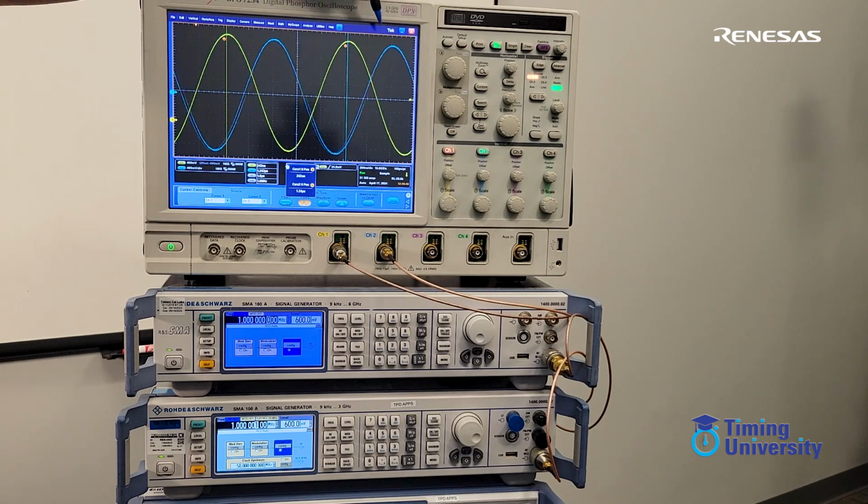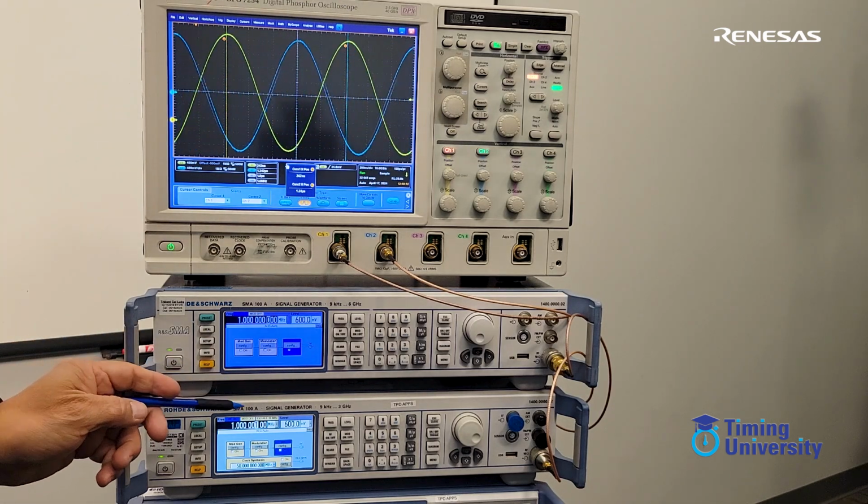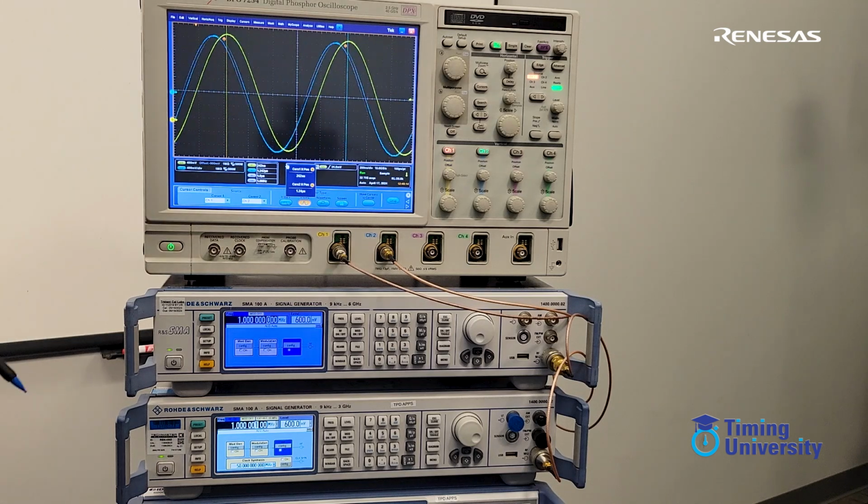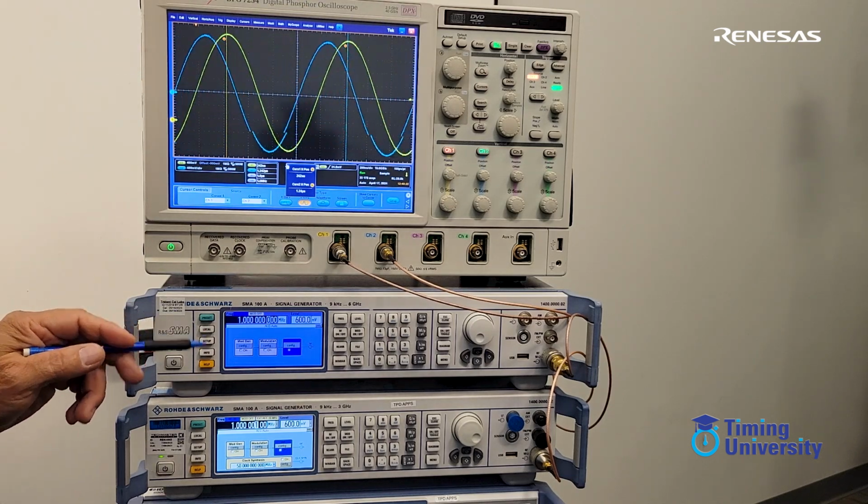Now we can actually quantify the frequency deviation by looking at how quickly this edge moves. It actually takes 1 second for this blue edge to move from this peak to this peak. So we measure it here. Again, we can measure it starting here, and it takes it 1 second. And that deviation, or that distance of phase, is actually 1 microsecond. So mathematically, it's 1/1,000,000th of a second, or 1 ppm. And look, coincidentally, our offset is 1 hertz over 1 million. So again, 1 ppm.